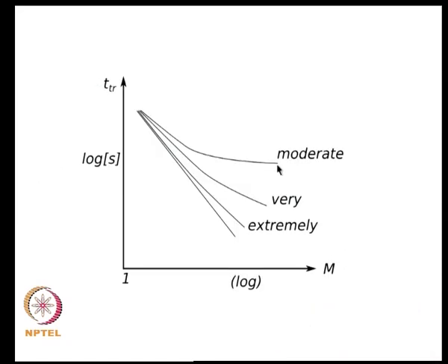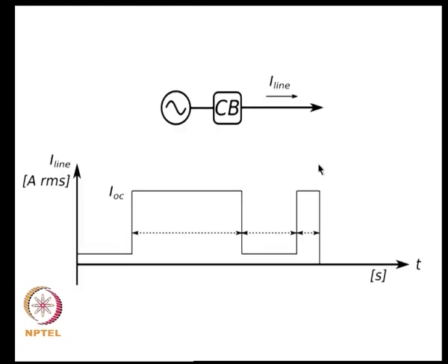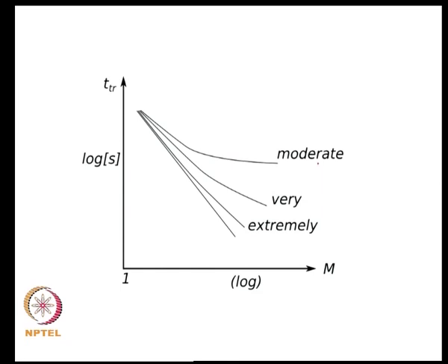Having a finite positive value of b essentially shifts the characteristic to a finite value, which says that no matter how large your current is, it needs a certain delay before the actual protective device can act. So, this sort of characteristic can allow a large amount of current to flow for a short time without tripping the breaker, but if that large amount of current continues for much longer, then the breaker would trip.